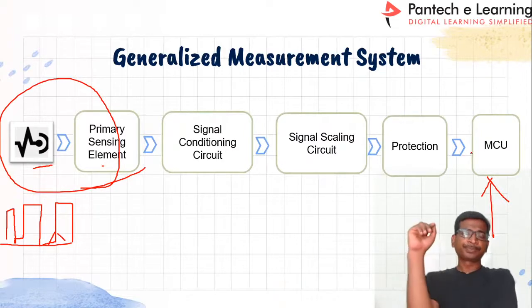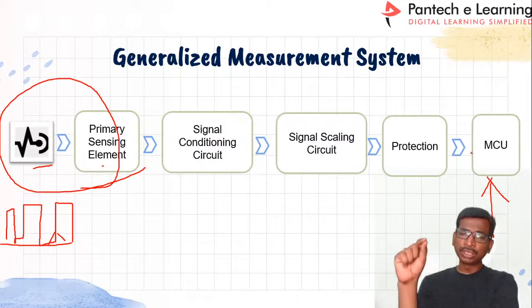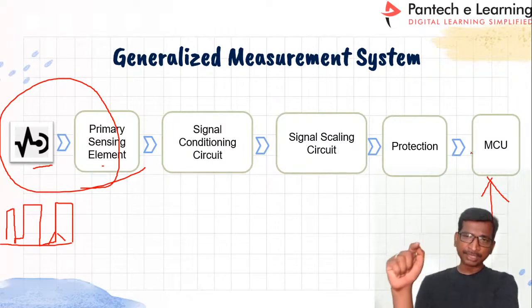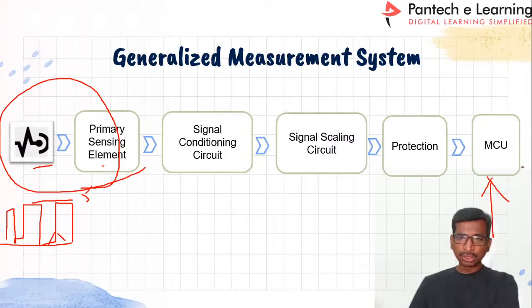See, actually microcontroller operating voltage varies. Like the 8051 will work under 5 volts, whereas if you take FPGA processors, then it will work under 1.2 volts sometimes, and then 1.8 volts. Similarly for the DSPs, 3.3 volts. So you have to generate whatever the input voltage is for this board. Let us take 5 volts. If you are going to use the DSP board, the DSP board will work under 3.3 volts.